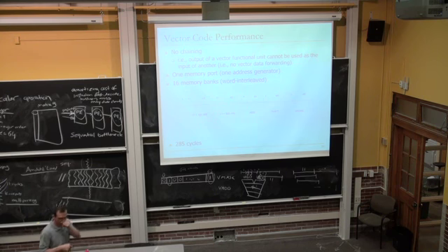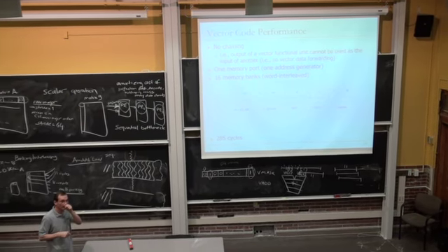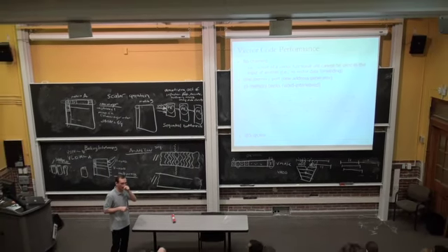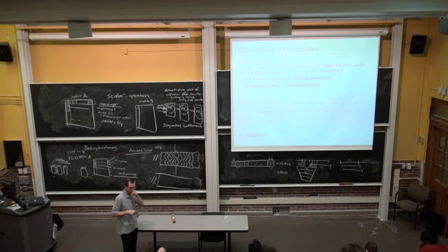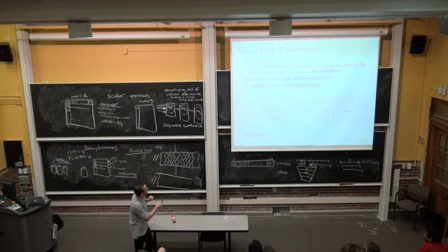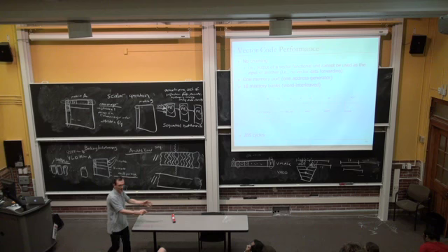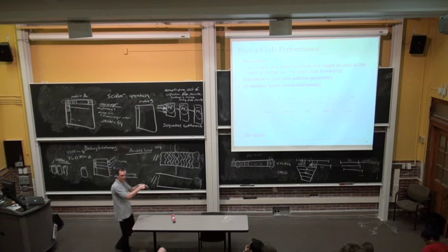I have a question about the basic coding. It seems to me that you'd always have multiples of 11 for the amount of times it would take to read values. If you had 11 cycles, that would give you 16 elements. If you had 22, that would give you 32 elements. So one of the banks takes 11 cycles, right? The bank itself takes 11 cycles to access. So if the next access goes to the next bank, you can start that access in the next cycle.